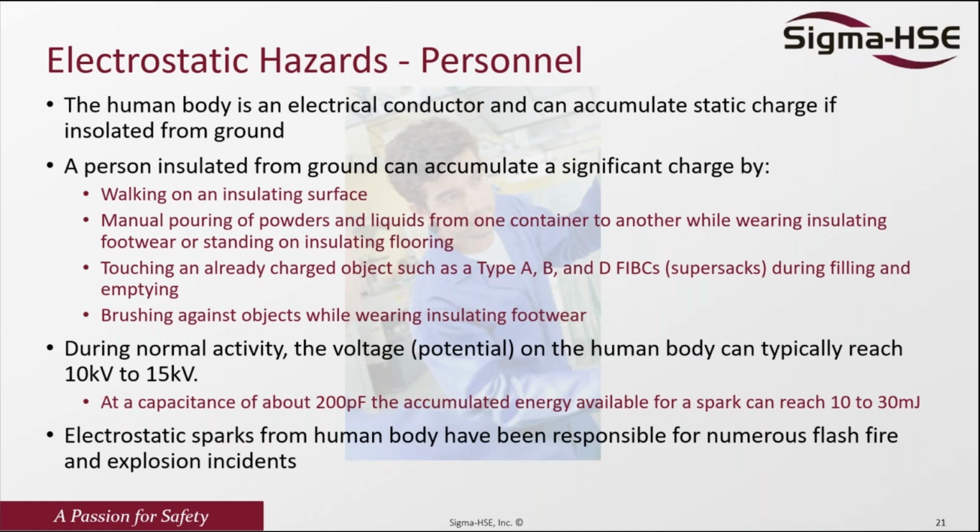And if the ignition energy is less than 30 millijoules, you can be engulfed in the flammable atmosphere because you are dumping under an abnormal situation. Maybe a cloud is going to form around you, whether vapor or gas or dust. And if you're not grounded, you can discharge enough energy that could actually ignite this material.